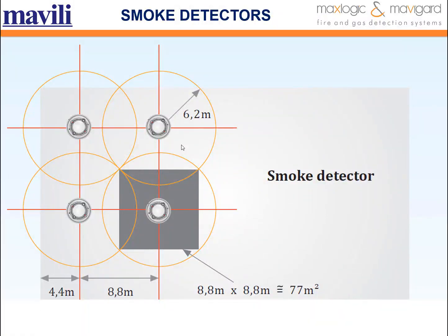When it comes to smoke detectors, the ionization chamber and optical smoke detectors both have sufficient response for general use. However, it carries certain risks, whether each type is suitable or not. Although both types are approved according to EN 54-7 standards.